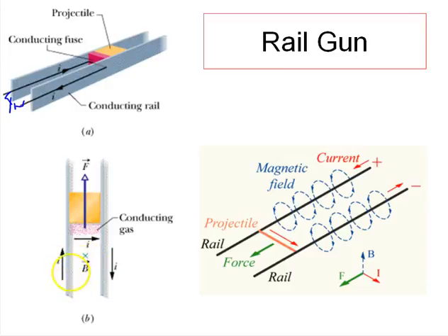As that current flows, if we take a look at this diagram, we can see the direction of the magnetic field due to both of these currents between the 2 rails is going to be into the page. We show that with an X, and you can show that with your right-hand curl. So if we have here a magnetic field flowing into the page and a current flowing to the right, then our magnetic force is going to be pointing upward.